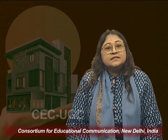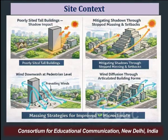In this slide you can see a few examples where tall buildings create shadow impact on the site, because the higher the building, the longer the shadow it will cast, and it can be mitigated by properly aligning the setbacks, properly creating some massing around the site, so that the solar conditions and the prevailing wind conditions are taken into care. Massing strategies are used so that the microclimate is better and improved site decisions can be taken.